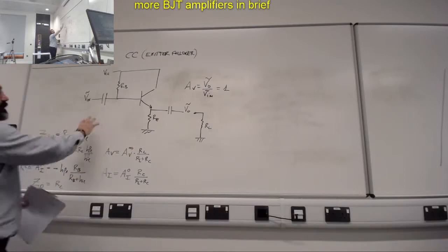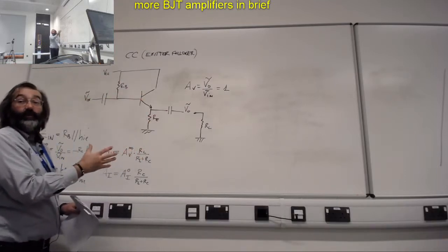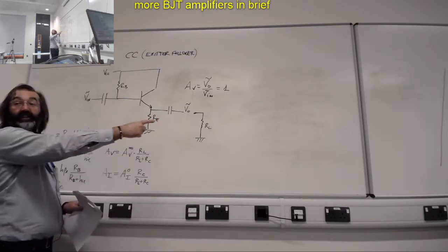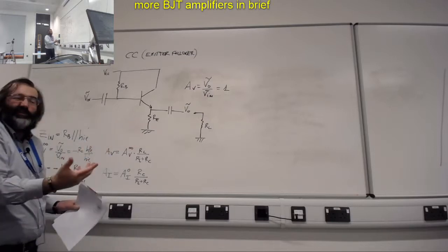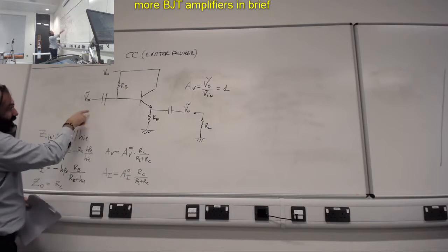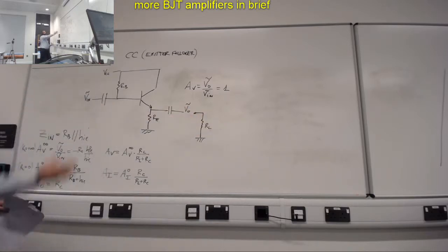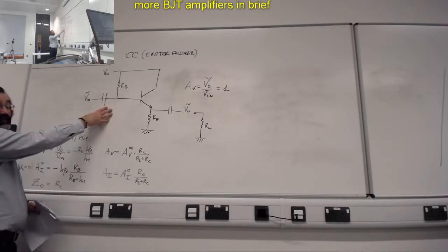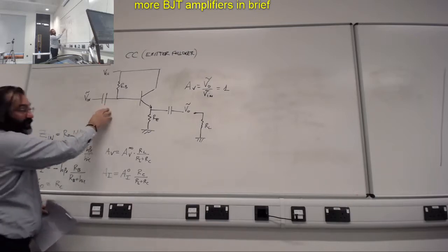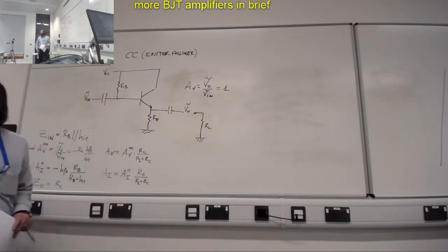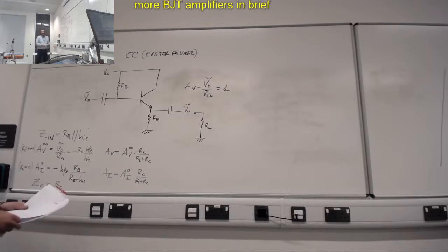The only reason why this could be there is probably to amplify the current. So you keep the voltage the same, but you amplify the current. So effectively what you're doing is you are changing the impedance of this circuit from input toward output. Probably the input impedance is high, so you have a very small current going in. The output impedance maybe is small, so you have a larger current going out. So this kind of operation, we will see in a moment.